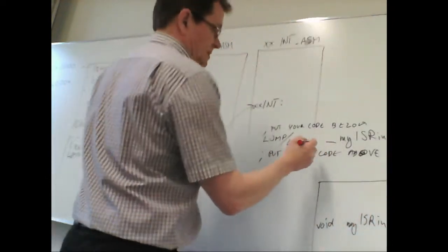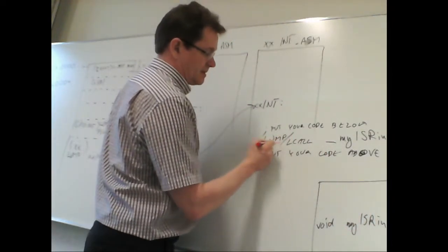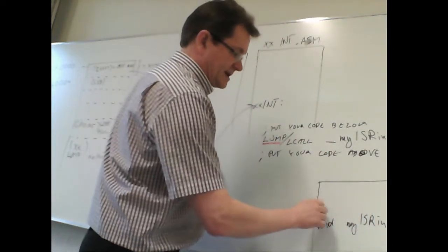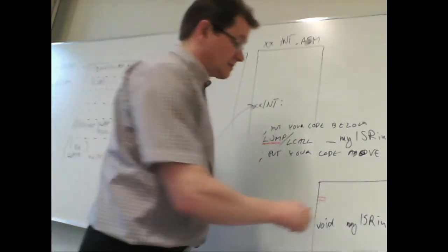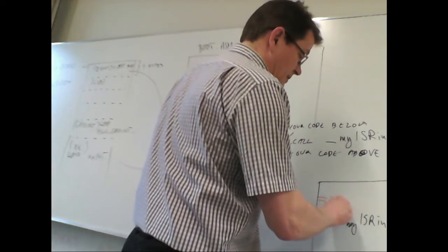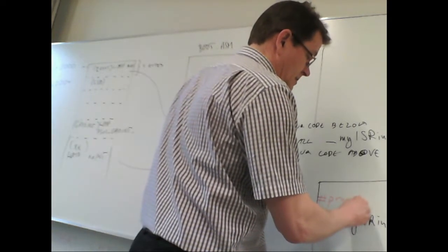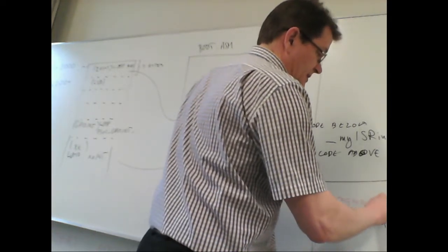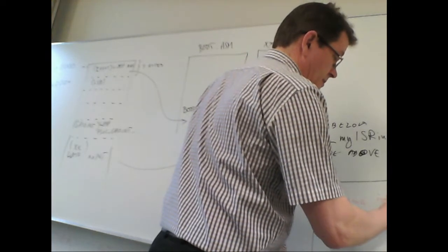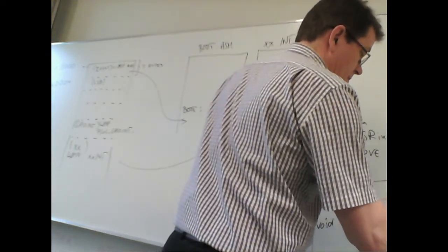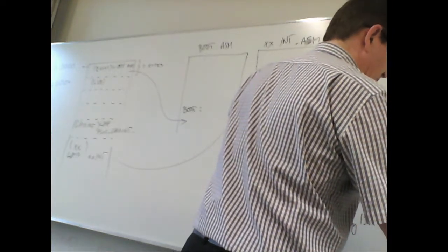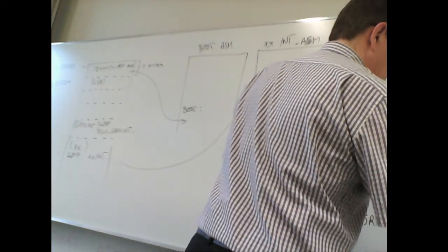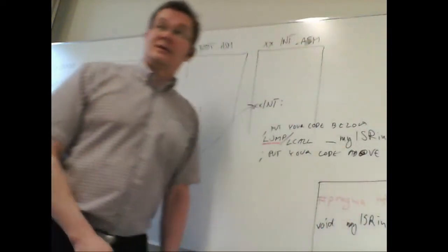If you are using long jump, then you must have a pragma statement, which is again a compiler directive for extra stuff: pragma interrupt handler and then the name of that function. It doesn't fit in here anymore.